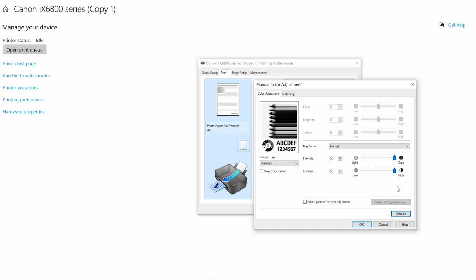It is still challenging, even with one film. And then you are able, with the right exposure settings, to get a perfect result. You can't go with 2 films. As I mentioned, we are talking about tolerances at a molecular level, I think, and even small shades and height from the ink to photoresist impacts, and the thickness of the film also impacts all your final resolution.